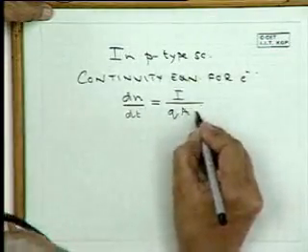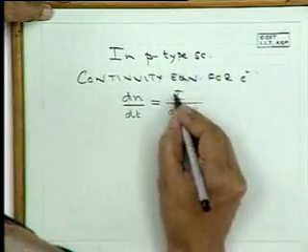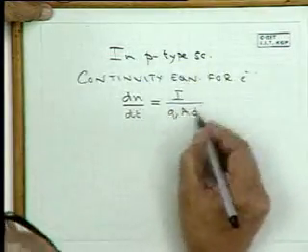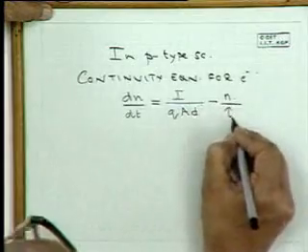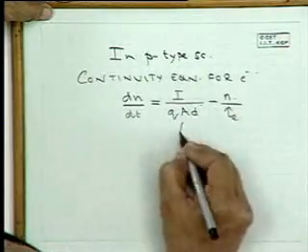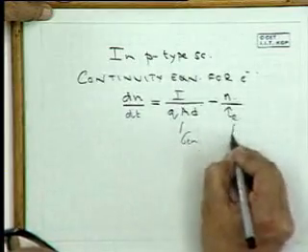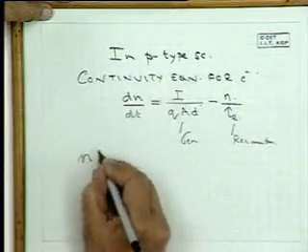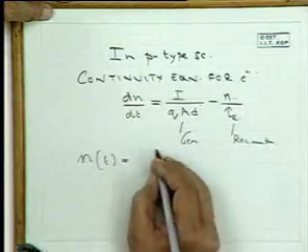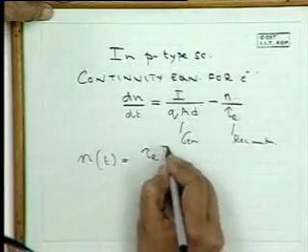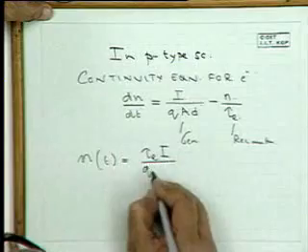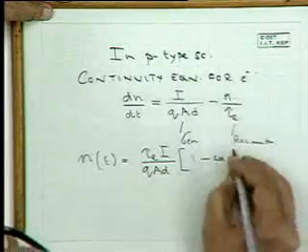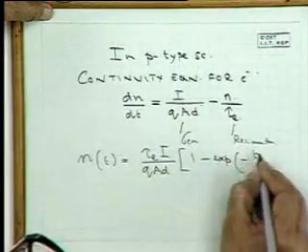Okay, so the generation rate is the injected current into volume, and this is just the number minus n by tau e. So this is the generation rate, and this is the recombination rate. If we solve this equation, we find that n(t) is tau e I over q a d times 1 minus exponential, and obviously you'll expect an exponential variation, minus t by tau e,